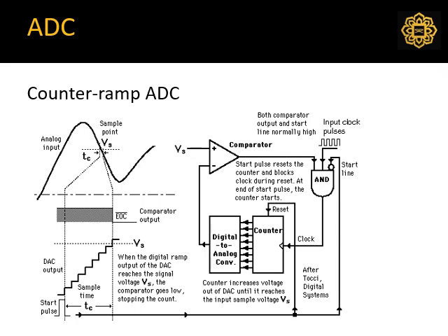So at every time interval you increase the counter value and you get the next closer value of the Vs, until you get as close as possible depending on the resolution of Vs. Now, next one is the successive approximation ADC.